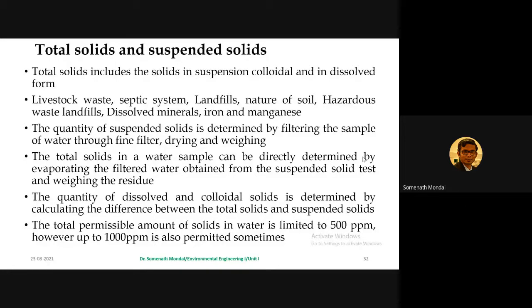Sometimes, what we can do is put the entire water sample into the muffle furnace, and then after getting it fused in the muffle furnace, we can check the weight of the residue in order to get the total solids present in it. Whatever organic solids are there will get decomposed in the muffle furnace, whereas only inorganic solids will remain.